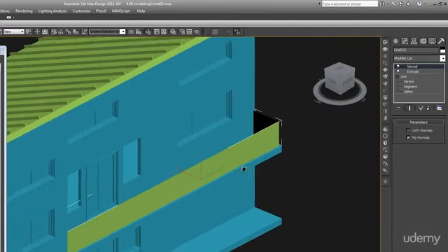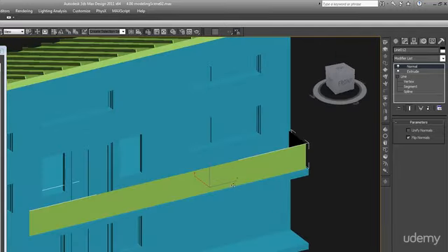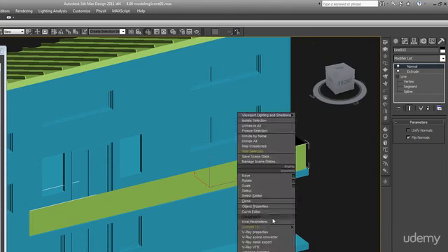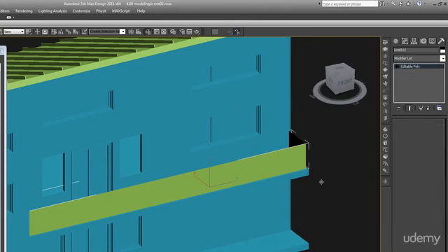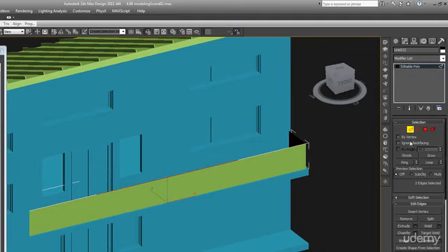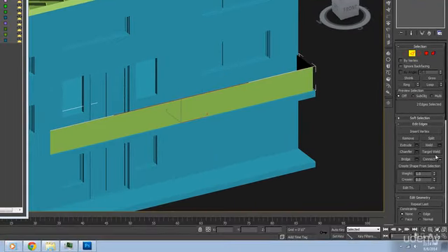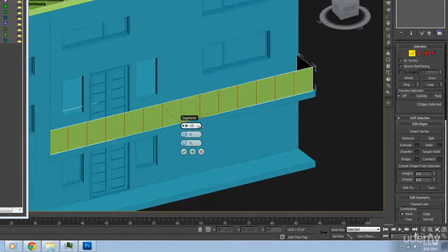Put the normal modifier on again. Now, last time I showed you to divide up the spline and then extrude it, and it gave you the verticals. Here we can just convert it to edit poly, and this is another way to do it: just select these two edges in edge subobject mode and hit connect. And this will show you exactly how many rails you're going to get.